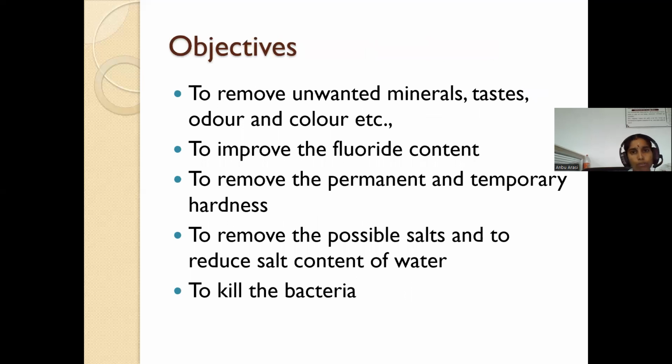Next, objectives of advanced water treatment plant. To remove unwanted minerals, taste, odor, and color. Unwanted minerals means iron, manganese, and fluoride. Unwanted gases are also removed in this process, that means carbon dioxide and hydrogen sulfide. Also to remove the fluoride content, to remove the permanent and temporary hardness, and also to kill the bacteria. Finally, to remove the possible salts and reduce the salt content of water.